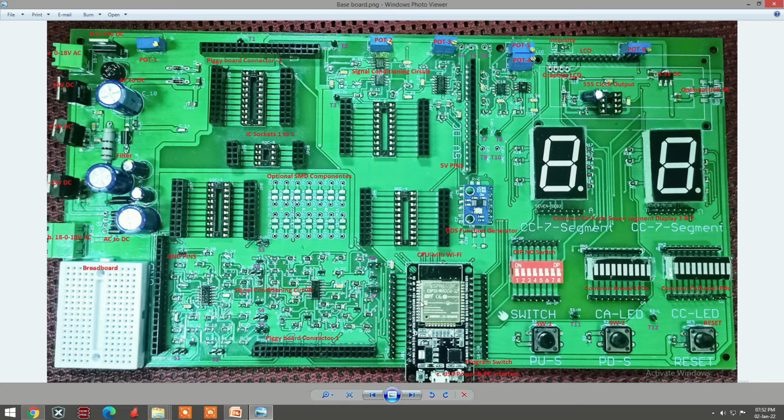And as I said, we have some other requirements like wireless communication, multiple ADCs, multiple DACs, multiple GPIOs, a good amount of memory, and high-speed computation. So we have to look at all these aspects while choosing this CPU. All right, this is the heart of the system, because it is acquiring the data and communicating the data, and of course equally responsible for display of the data.